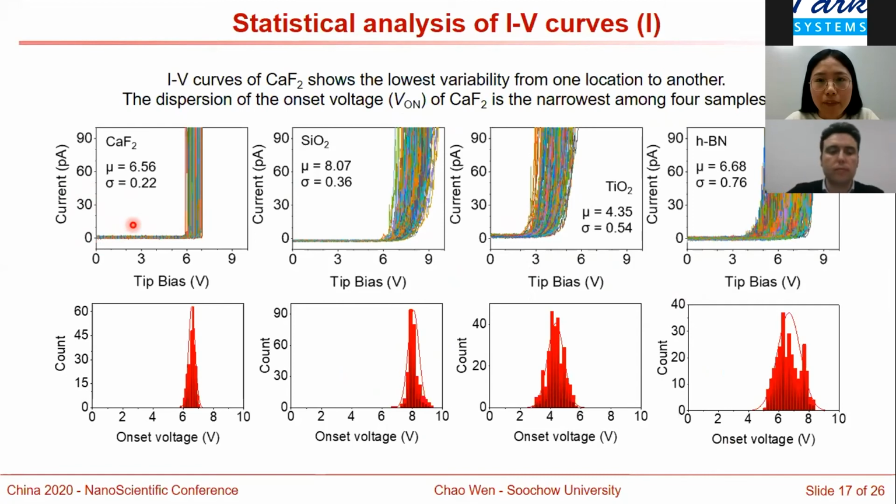We didn't see any visible defects in our SThM images, but in silicon dioxide and especially CVD hexagonal boron nitride, we can see a lot of amorphous defective regions. So those defective regions cause the electrically weak spots, which cause the leakage currents. Here we have a lot of leakage currents, but in calcium fluoride, the film is grown by molecular beam epitaxy and is of good quality and defect-free over large regions. That's it.